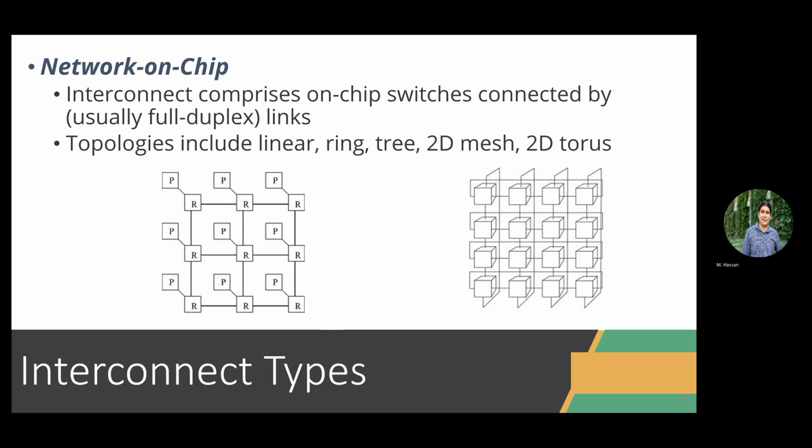Good. And then we have the most advanced thing, or the general thing, which we call network connection. This is, by the way, what we have in most modern systems, including Tesla, as you've seen, including modern FPGAs from Xilinx or Altera/Intel, including Xeon processors. Network connections are solving a lot of scalability issues. So right now, I'm generalizing the system, mimicking general networks. You might not be aware of NoCs, or network connection, but you are definitely aware of general networks, like for example, the internet.